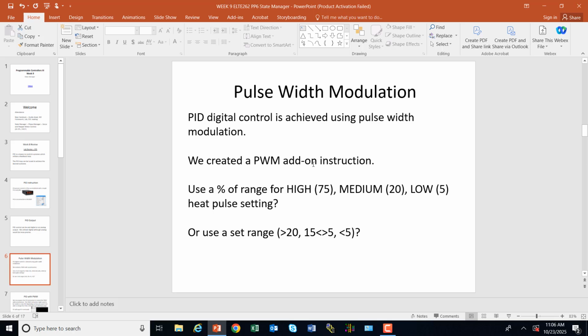But that's a good little example of going back to 110, where you might just use your Ohm's law to calculate the amp draw, because that light bulb is just a pure resistive circuit. It's just generating heat, and we don't need to do any AC math on that. It's just straight-away DC Ohm's law math.